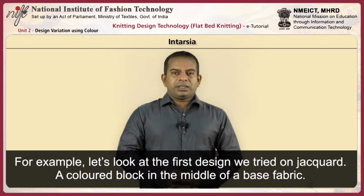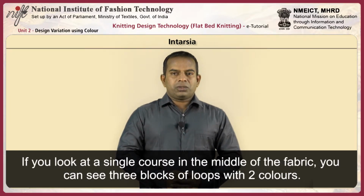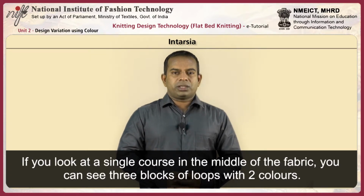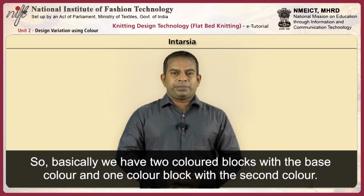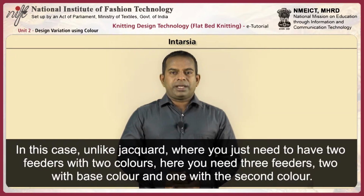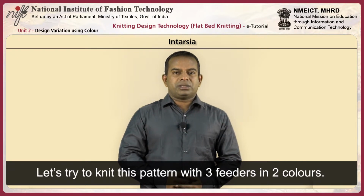For example, let's look at the first design we tried on jacquard, a colored block in the middle of a base fabric. If you look at a single course in the middle of the fabric, you can see 3 blocks of loops with 2 colors. So basically we have 2 blocks with the base color and 1 block with the second color. In this case, unlike jacquard where you just need 2 feeders with 2 colors, here you need 3 feeders, 2 with the base color and 1 with the second color. Let's try to knit this pattern with 3 feeders in 2 colors.